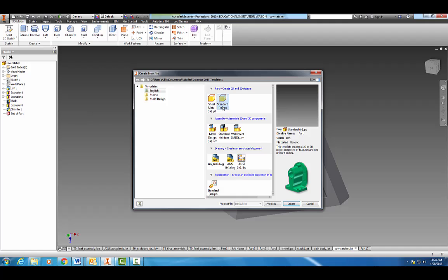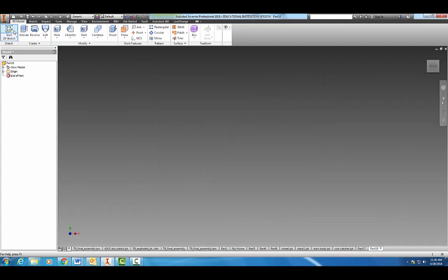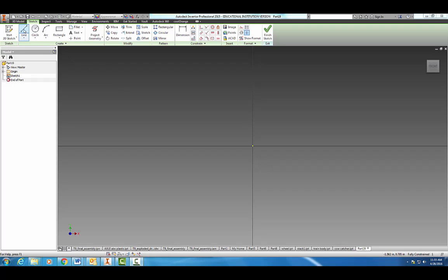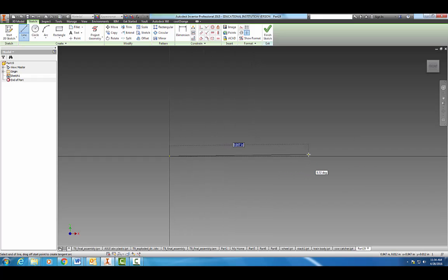start a new 2D sketch on the XY plane here. So what we're going to do is draw a 2D sketch out, and we're going to loft later on between two 2D sketches. So we're going to make kind of this home plate looking sketch from baseball. 1.8. We're going to make two sides on our line here with a length of 0.25.